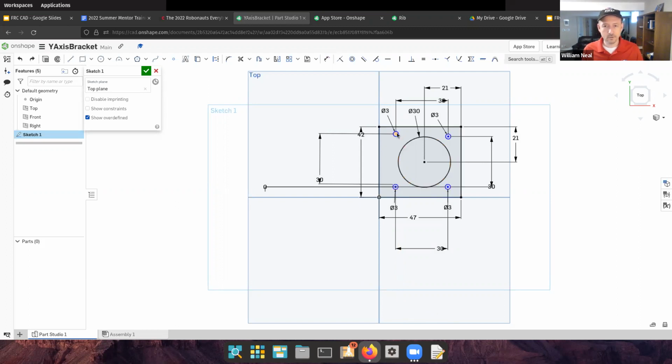Control Z, let's hold down Shift, select the 2 parts. Here we are. Select one, select the other with Shift down, and it's talking about that distance. I want the horizontal distance between them to be 0. Try these ones.